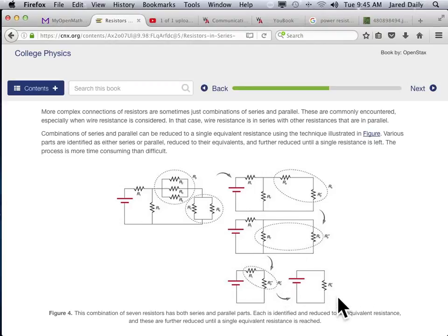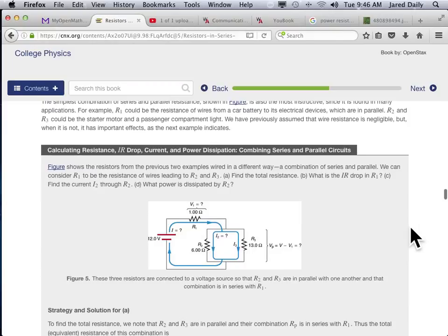And then once you're there, if you know the voltage and the current, or the voltage and the resistance, you can calculate how much current is going to go through this total circuit. Once you know the current that's going through this resistor, then you can figure out that it's the same current through these two because they're in series. And then you can figure out that it splits between these two in parallel. And you know how that split works because we just did the math. Well, anyway, let's do an example and show you how it works.